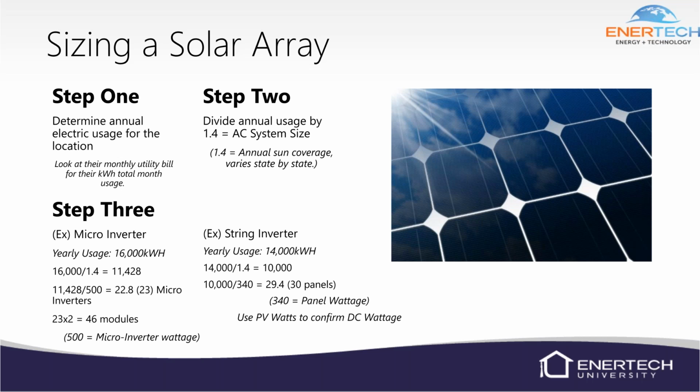So we could potentially need up to 46, depending on the wattage of those panels, if those are low wattage modules in that particular case. But in a string inverter case, we could actually use higher wattage modules and one inverter to put more DC coming at that inverter on that particular system. So less panels.